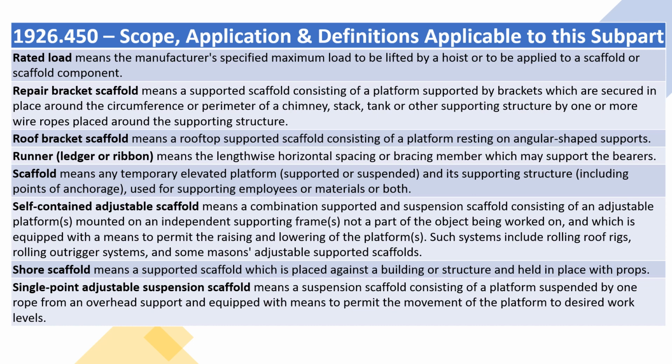Scaffold means any temporary elevated platform, supported or suspended, and its supporting structure, including points of anchorage, used for supporting employees or materials, or both. Self-contained adjustable scaffold means a combination supported and suspension scaffold consisting of an adjustable platform mounted on an independent supporting frame not a part of the object being worked on, and which is equipped with a means to permit the raising and lowering of the platforms. Such systems include rolling roof rigs, rolling outrigger systems, and some masons' adjustable supported scaffolds.